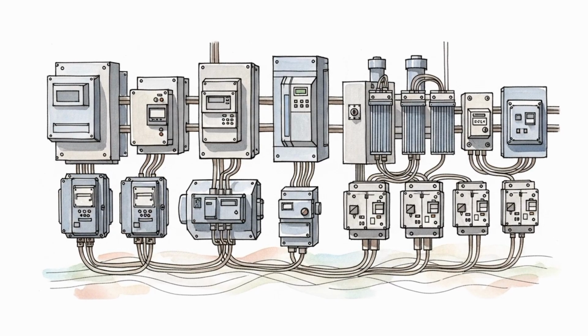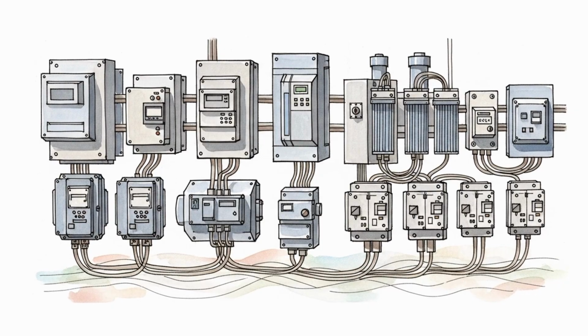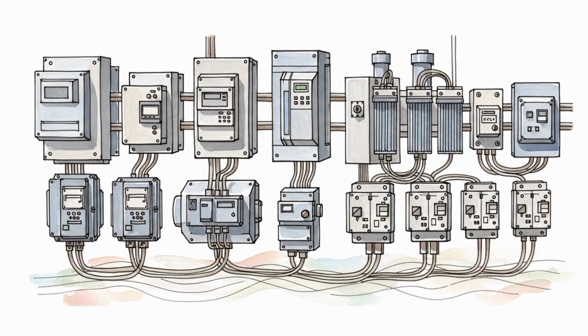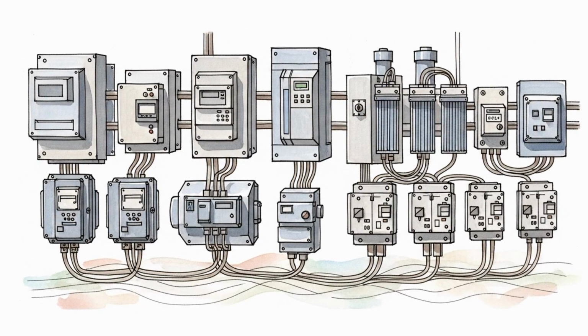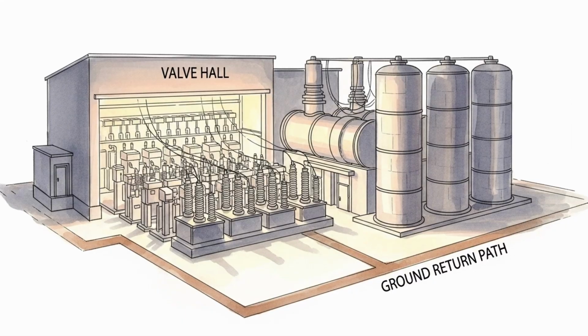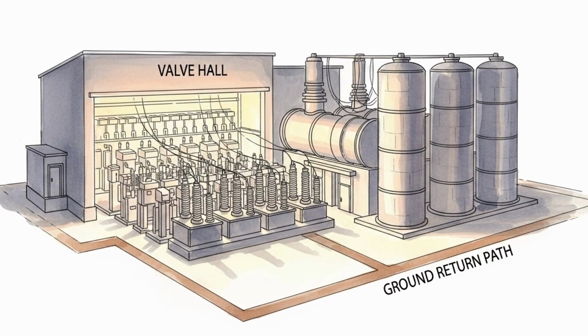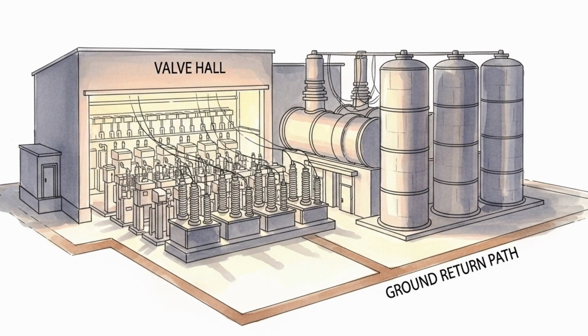Modern satellites use error detection and correction in memory, periodic memory scrubbing, watchdog timers, and redundant processors to contain these effects. Field programmable gate arrays are protected with configuration scrubbing. Software restarts keep services available but can reduce duty cycle during the storm.